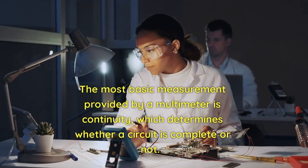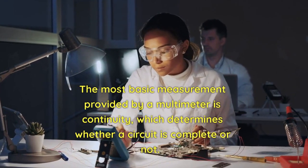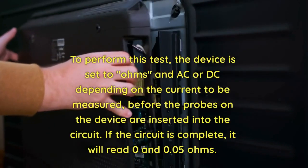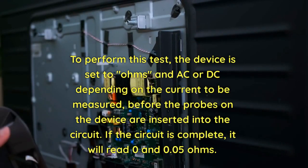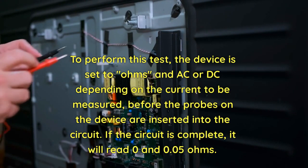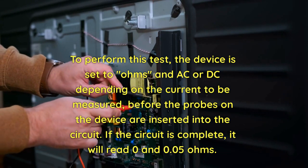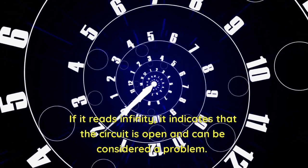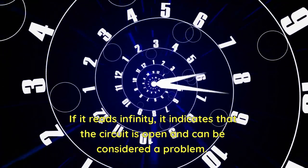The most basic measurement provided by a multimeter is continuity, which determines whether a circuit is complete or not. To perform this test, the device is set to ohms, and AC or DC depending on the current to be measured, before the probes on the device are inserted into the circuit. If the circuit is complete, it will read 0 to 0.05 ohms. If it reads infinity, it indicates that the circuit is open and can be considered a problem.